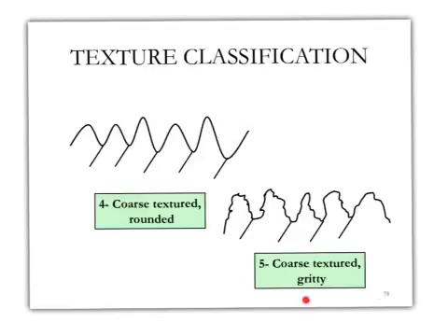So going now to this one, which I think is one of the preferred surfaces, is to have a coarse textured and gritty or irregular aggregates. So this is what I see now. It's coarse texture because again the distance between the highest point and the lowest point of one aggregate particle is high, and at the same time I am using irregular shaped aggregates rather than rounded aggregates.